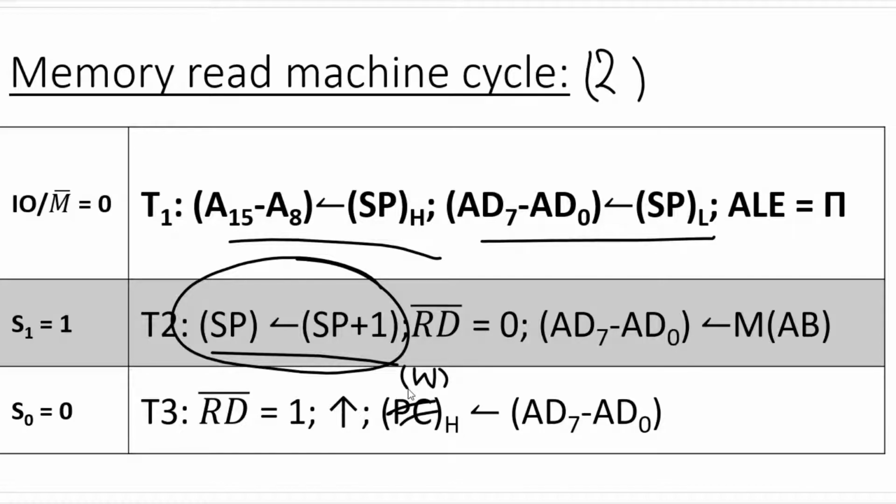Because if we write this data from the stack onto the HL register pair, HL will be overwritten, but we have to read from HL and store it on the top of the stack. Now the stack is actually free because whatever data was there has been stored in W and Z.